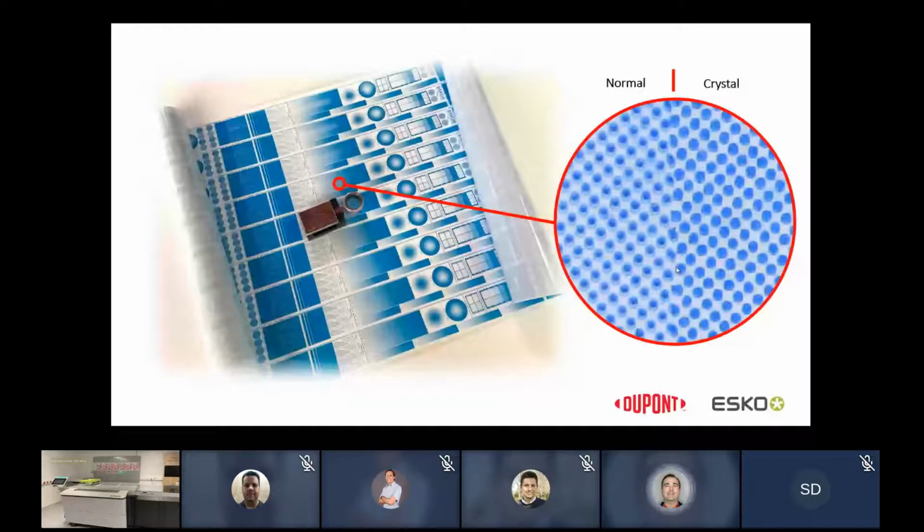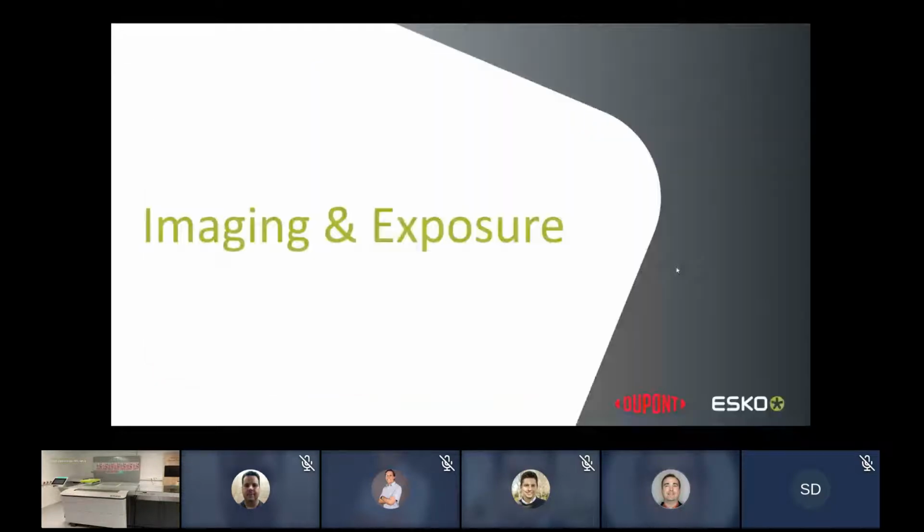You've got a clear distinction between dot and paper that you don't generally have with fluid inks and flexo. So there's a lot of power here. You're going to get much cleaner tone reproduction. You're going to stay cleaner on press, with less dot bridging. Very interesting results. And again, Mark Samworth and Corey Devlin will go deeper into that during their presentation.